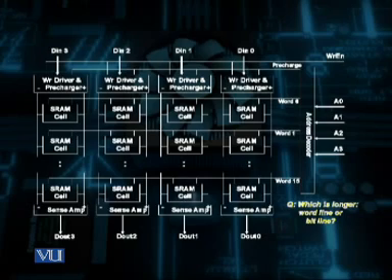Furthermore, the internal logic will detect an address change and pre-charge the bit lines. Once the bit lines are pre-charged, the values of the new address will appear on the D out pin, that is the data output pin.